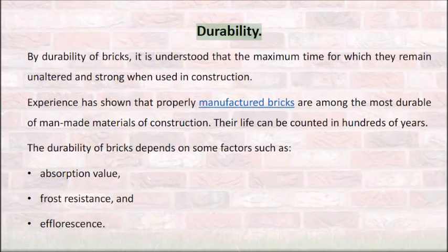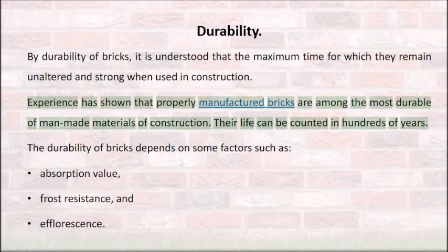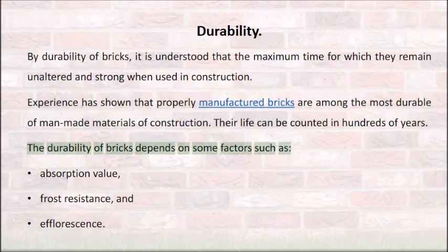Durability. By durability of bricks, it is understood that the maximum time for which they remain unaltered and strong when used in construction. Experience has shown that properly manufactured bricks are among the most durable of man-made materials of construction. Their life can be counted in hundreds of years. The durability of bricks depends on some factors such as absorption value, frost resistance, and efflorescence.